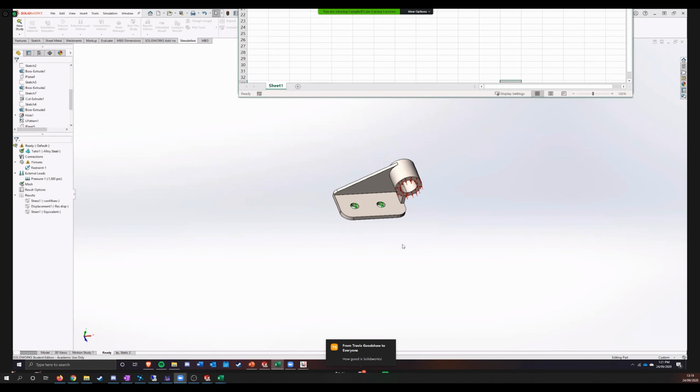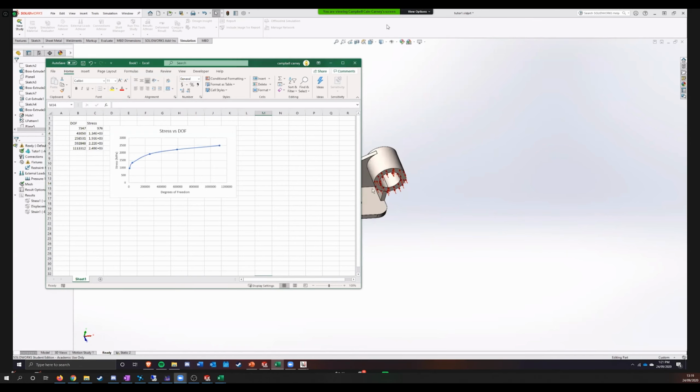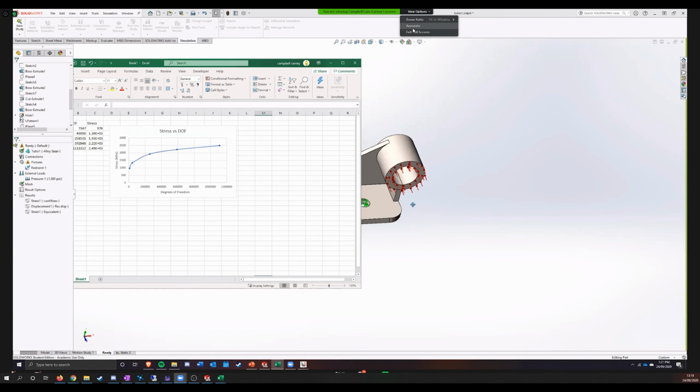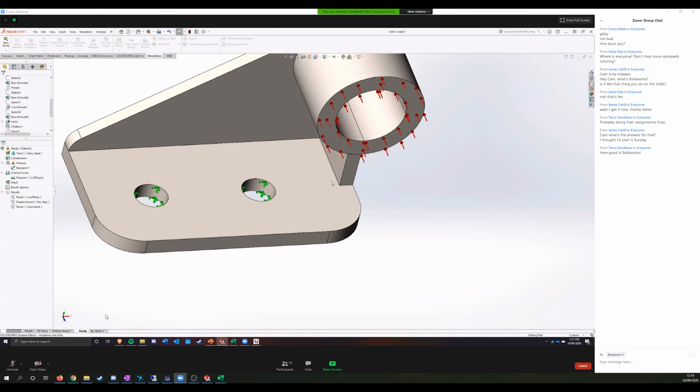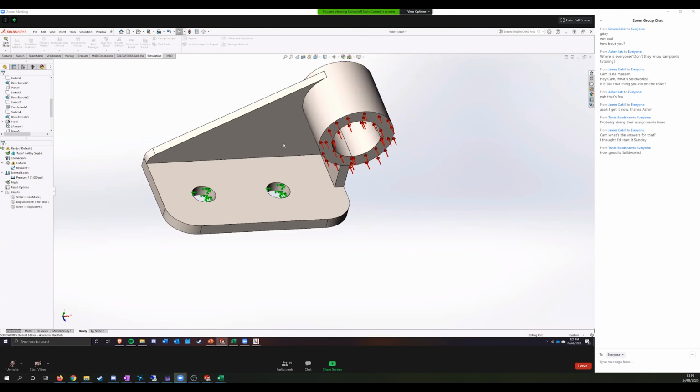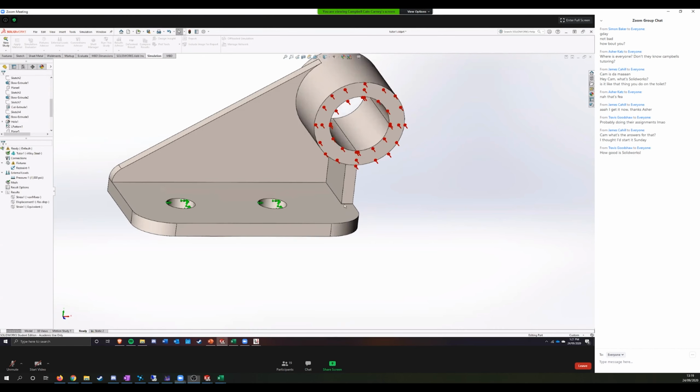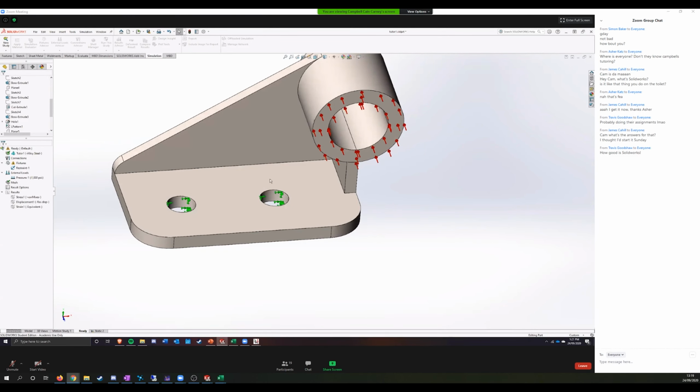What I've done is plotted the stress at this point specifically. So I know the document asks you to plot where the max stress is, but you will notice that sometimes the max stress can be around the bolt hole as well. When you're looking to check a singularity and check that the singularity actually is behaving the way that you want it to, or maybe not.